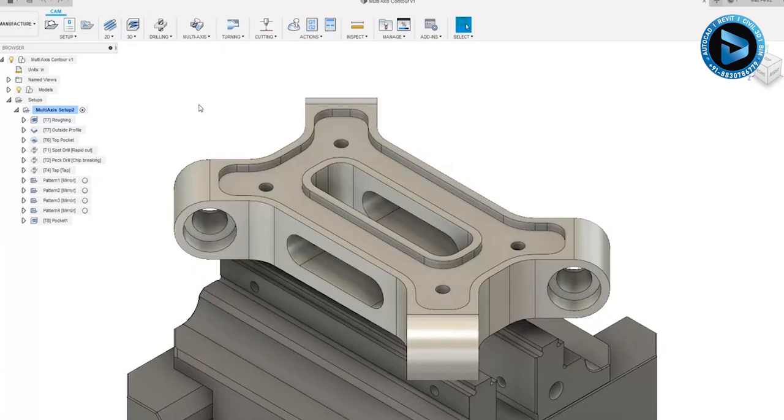This is the same file we used in the previous week's lessons, but now we want to start to explore some simultaneous multi-axis toolpaths. So far, when we machine this part, we used multi-axis positioning, or 3+2 machining. This means that we were machining in 2 and 3 axes, but using the additional A and B axes for rotation to position our tool. Now we want to explore how the tool can move in all axes simultaneously.